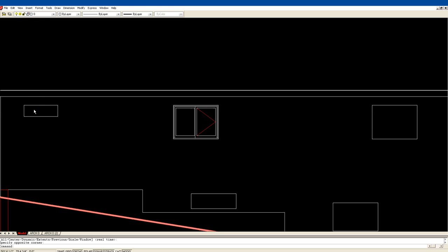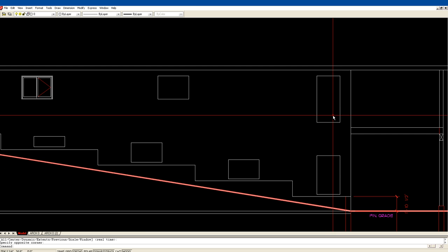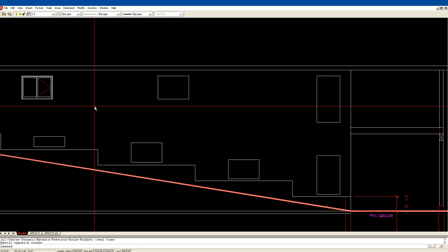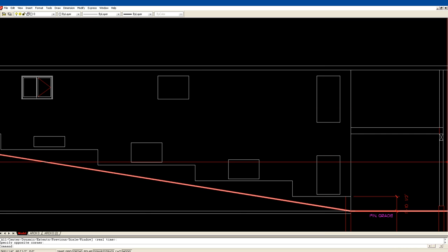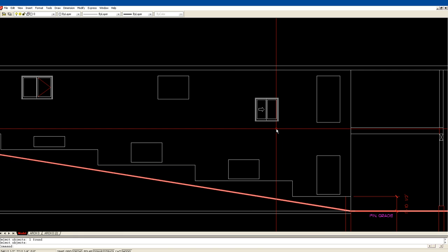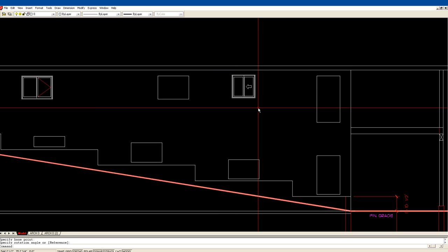Here I would be a slider, or this could be glass block. When I got to these big ones, if I wanted that window to open, okay, I'm just going to bring in another window here. Okay, and I'm going to explode it first this time, and then I'm going to rotate it. Pick this corner and go up like that.